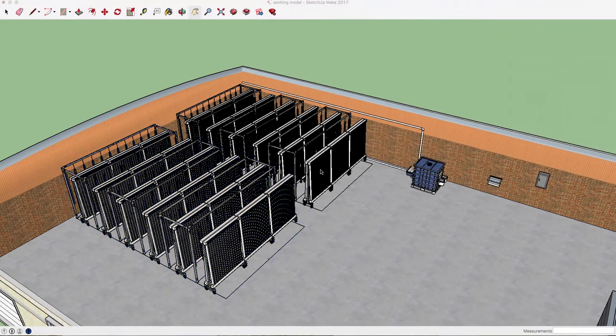So a couple quick pointers here. We recommend keeping your plumbing, supply, and drain lines in a straight line if possible. We also recommend that you avoid too many 90-degree turns or twists in your plumbing line. And the reason is that we are trying to keep the pressure at recommended levels throughout the entire ZipFarm. We would like for the zip racks here at the end of the line to be getting just as much pressure as those at the front. And when you install your ZipFarm, you'll see how this works. These zip racks can be connected to your supply lines and drain lines with some simple quick connect fittings.